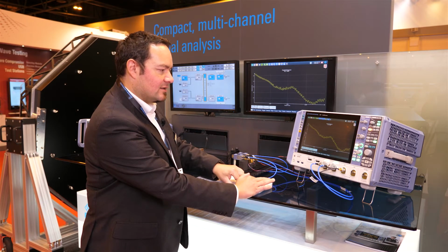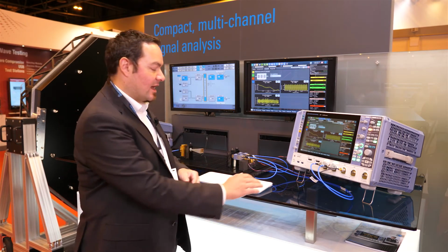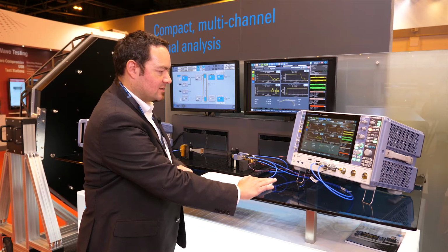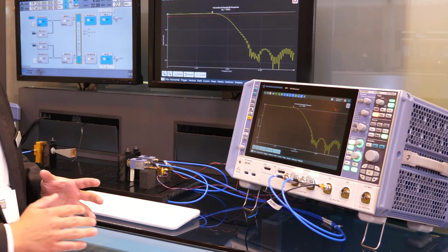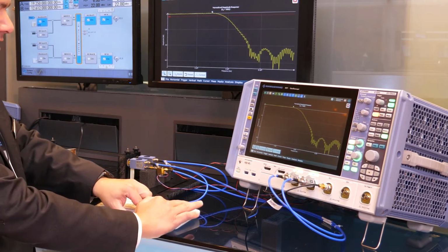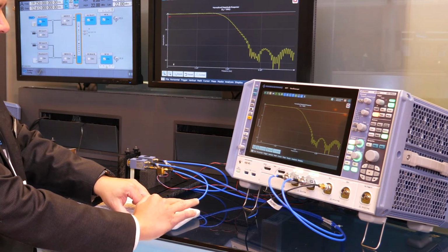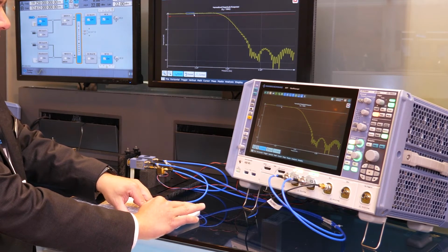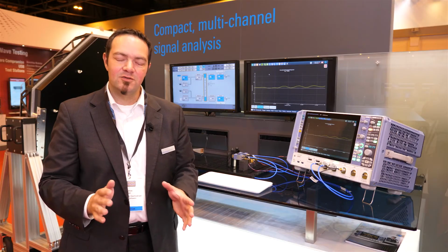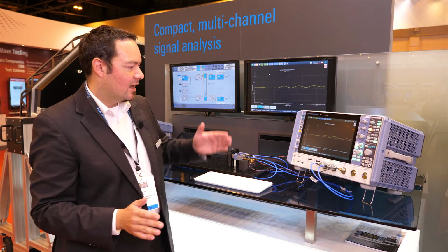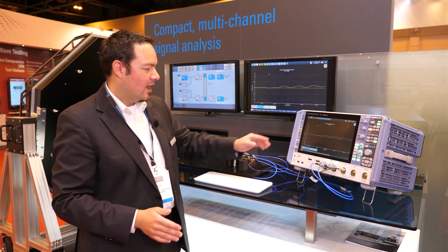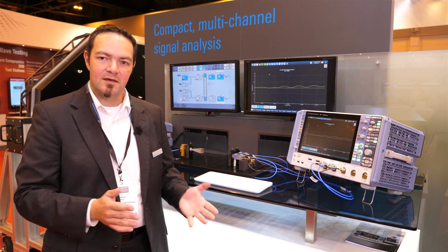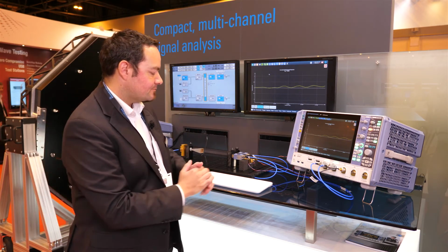What the de-embedding in real time is giving me as a result, based on this curve, is a very flat response. And just to give you an impression how good this is, I open the magnitude response curve, I apply a small zoom, and then you see that based on this 15 to 20 dB of conversion loss, the algorithm, the real-time de-embedding, is correcting this in a very nice way so that the losses are less than 0.5 dB.